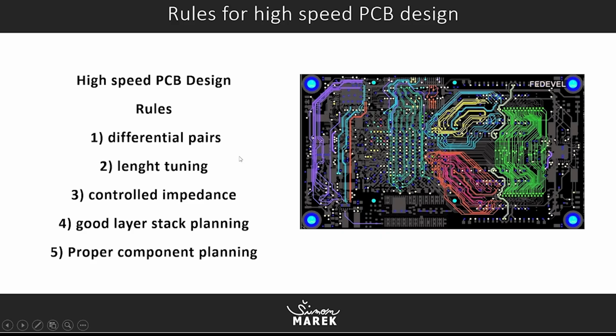So this is really differential pairs. Then there is length tuning, which is great for connections to memories and for buses and similar. So length tuning is very important.